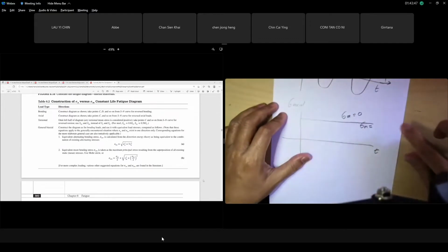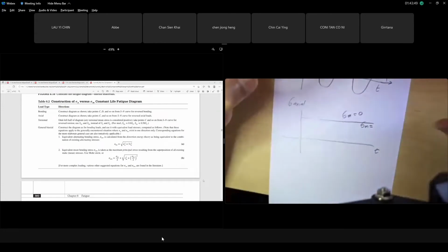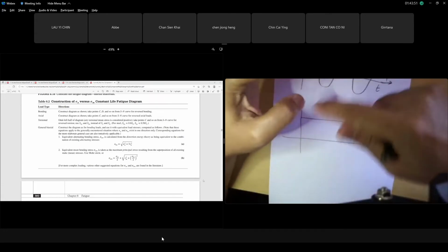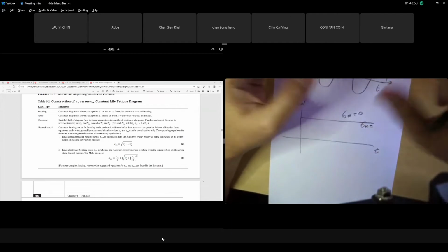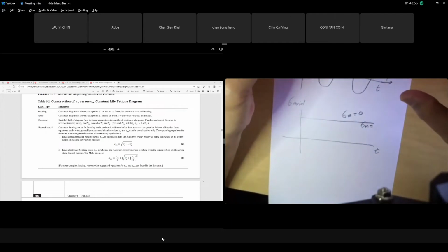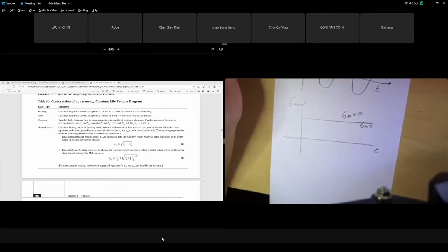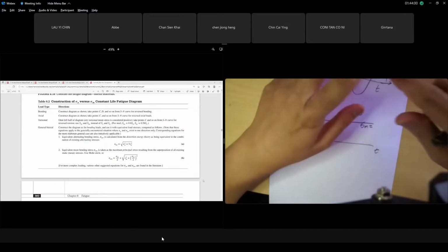It remains constant through time because axial stress remains constant, even if your element is rotating along the circle of the shaft. The shaft is rotating, but the stress remains the same. Uniformly, it remains axial stress along X. It does not change. But bending, yes.